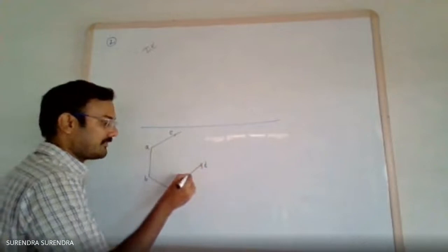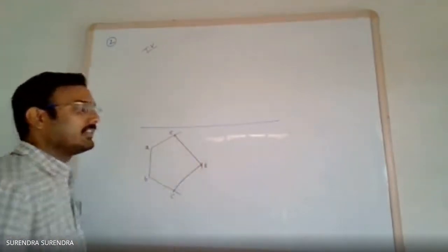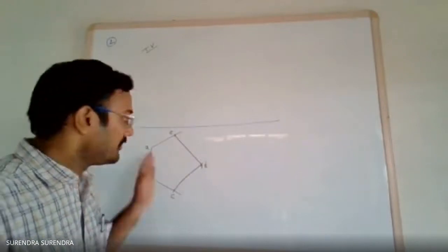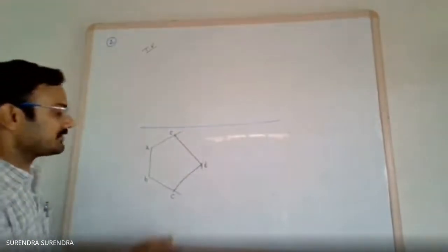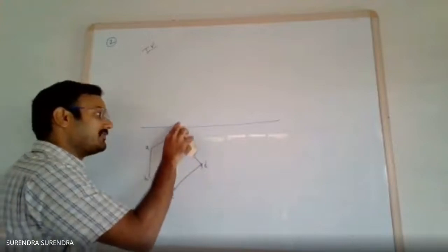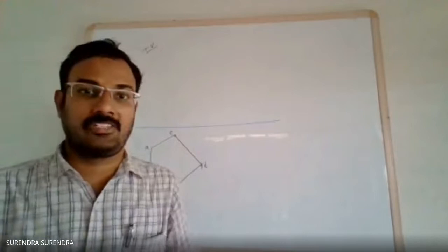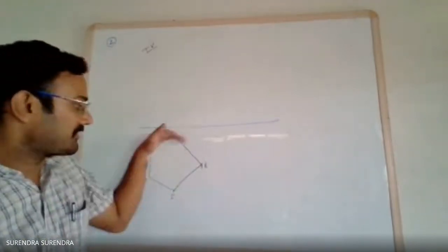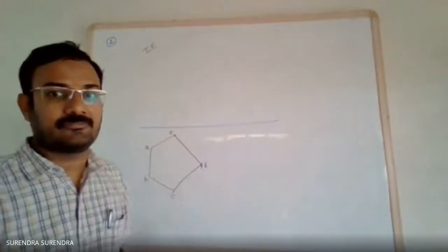Join DC and ED. We'll get the pentagon of required dimensions. First draw with a 2H pencil. Only highlight up to C. Here, don't erase; if there is extra, leave it. I am erasing on the board, but don't erase on the drawing sheet. The extension lines, if you get more than the line, leave it.